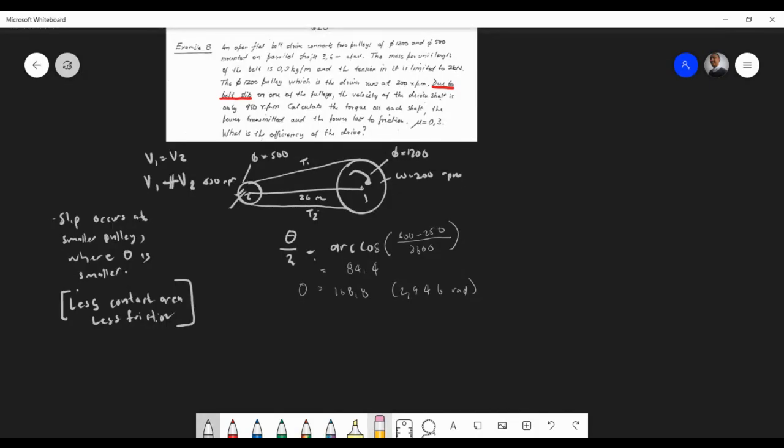So you know power, power equals T1 minus T2 times velocity. Because we have different velocities, we have to work with velocity 1, so it's power 1, T1 minus T2, velocity 2, right? So we need to get all of that going over there.